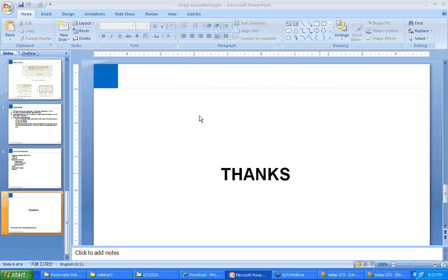But in that case, you need to activate the wall in that seepage test analysis, not in that construction stage test analysis where you are activating the wall, because the seepage phases can be reflected only in seepage steady state analysis. And if you want to follow that procedure, you need to activate all the structure elements along with seepage phases in a particular construction stage, which will be my steady state seepage. And then in the next construction stage, you make a dummy construction stage to adjust the stress level in the ground. And with that, we can see those results.